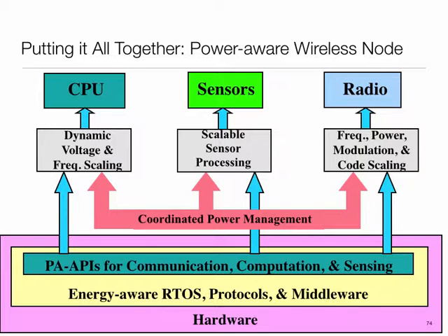Can you give another example of a sensor? I don't know, temperature, ECG, accelerometer, gyroscope. There are all these examples. For example, the sensitivity for the received signal; some sensors cannot work with low power signals and with high power signals. Mm-hmm, the sensitivity of the system. Yeah, sensitivity. So basically, what is the range of signals I'm willing to capture? How sensitive am I? Can I capture very low range signals, or can I afford to miss them out? So I can dial the sensitivity, which in effect affects the amplification stage, and I could therefore use that.